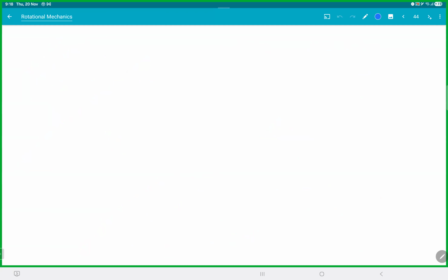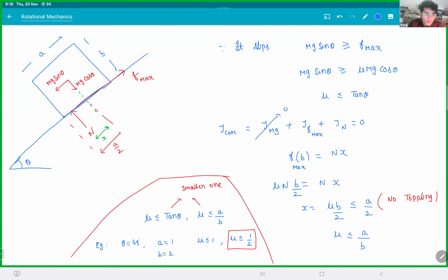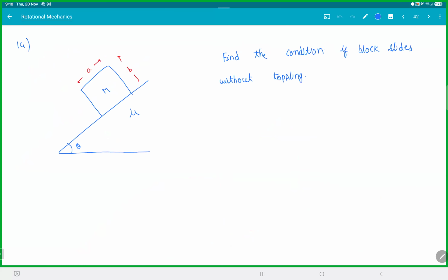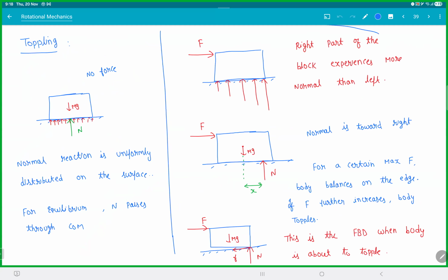Sir, I have a doubt: when we say the normal is shifting, can you please explain why the normal shifts? I got the mathematical approach. If you sit on the COM, then no other force is there to reverse the torque. You're not listening, yeah? When I explained the whole thing, I told you that story. If you shift to the right side, your weight will shift to your right leg. If you shift to the left side, your weight will shift to the left leg. N is not actually a single point, right? When you say normal is acting, it is not acting at a single point. For convenience, you take it at one single point.